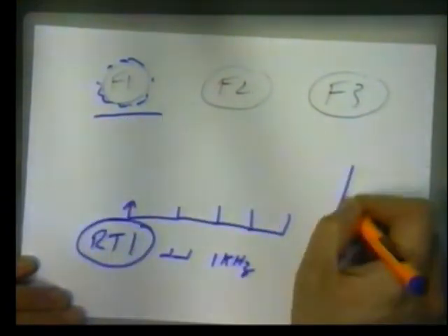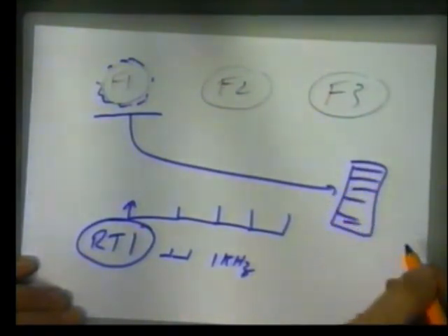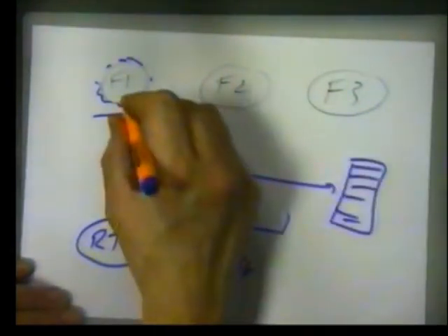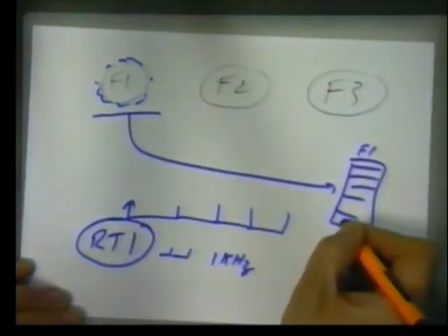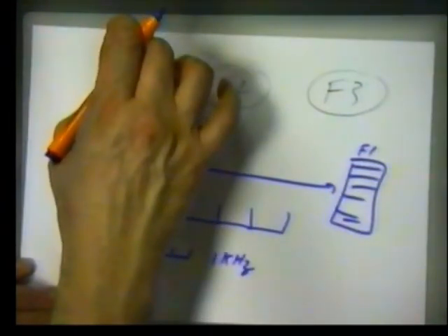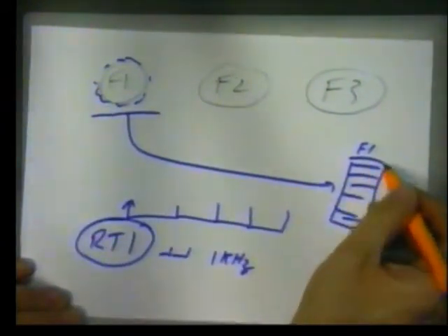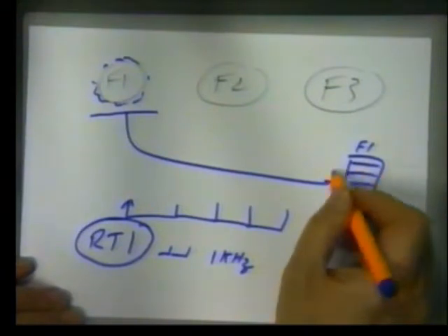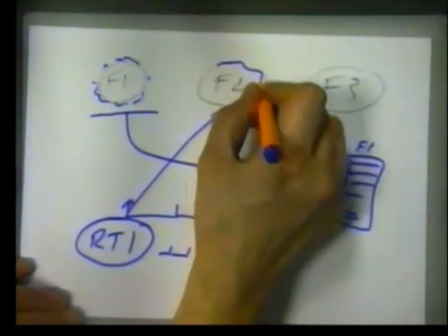And a copy is taken into a stack frame of all the registers and memory it was using. So associated with each function, there is a frame that belongs to the real-time interrupt. It suspends the operation of the current active task, keeps an image of what the processor was doing at the time it was suspended, and then it starts the next one off.